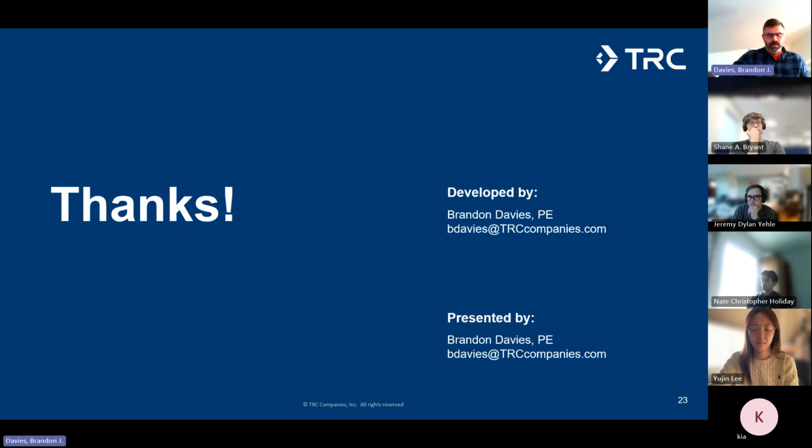like that, I assume UMaine has access to IEEE standards, but any of the IEEE guides are all really great references, and they're intended for early career engineers who are trying to learn more details about specific protection topics. So it's generally the IEEE C37 standard series, but they have guides for everything. They've got a guide for transmission line protection, a guide for line differential protection, a guide for bus protection, transformer protection, capacitor bank protection, and they're all really great places to look for that information.